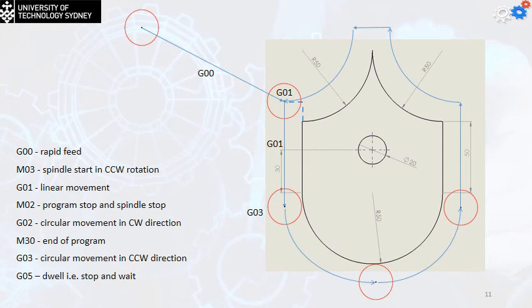Now I have to go back to G01 to do the cut for the other side, the right side of the profile. I have to go up to the end of the arrow with G01. Now why the end of the arrow? Because when I'm going to do the arc, I'm going to keep this corner clear. If I take it closer, I'm going to damage the work. I'm not going to have the same dimensions.